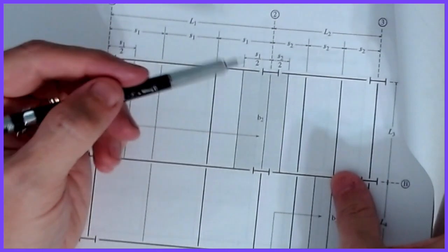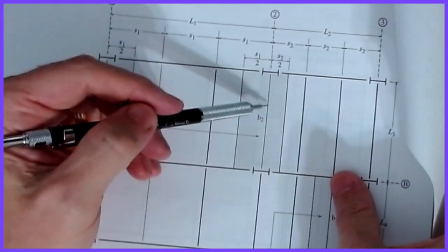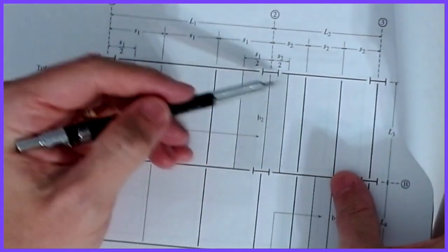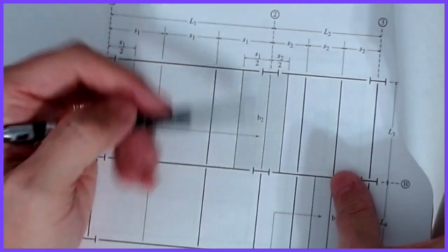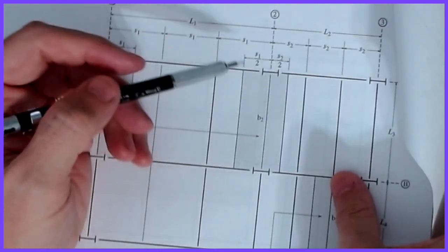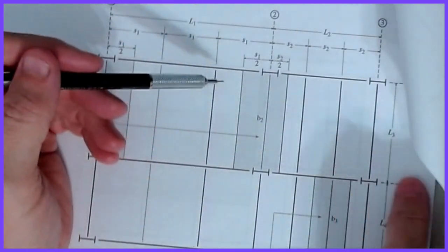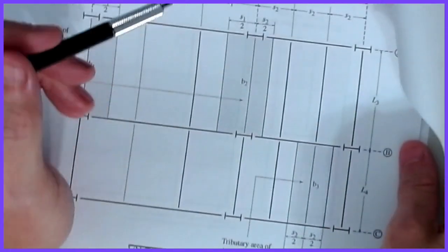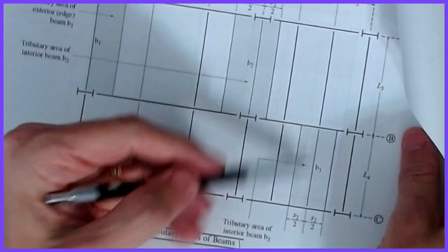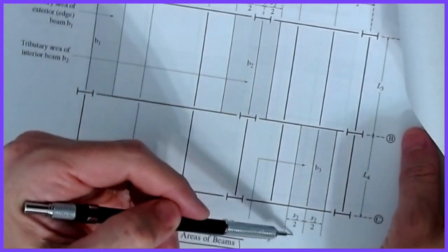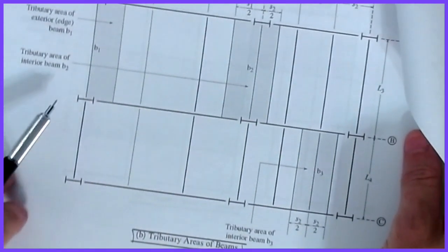Okay, but the beam that's in the middle between one spacing and the next will be an intermediate value between those. Now again, you don't have this problem if everything is the same spacing, but for this scenario. Then we can go back and look at our other interior beam on the other side, where S2 over 2 is now happening. So hopefully that's made some sense.